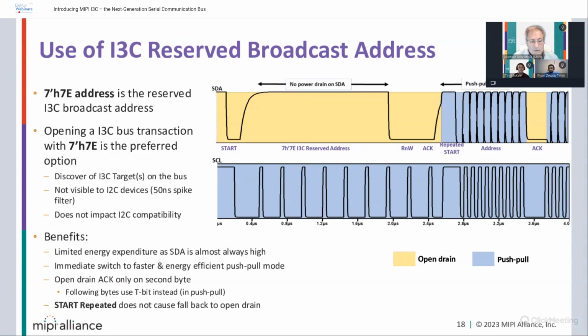You may also notice that the clock on the first part not only is slower, but it's kind of spiky. This is on purpose, it's not casual. There is a feature of I2C, from the old days, let's remember that I2C started 40 years ago. At that time, there was not really a specification, but a recommendation that has become a de facto spec, that I2C devices should ignore any pulse that is less than 50 nanoseconds.